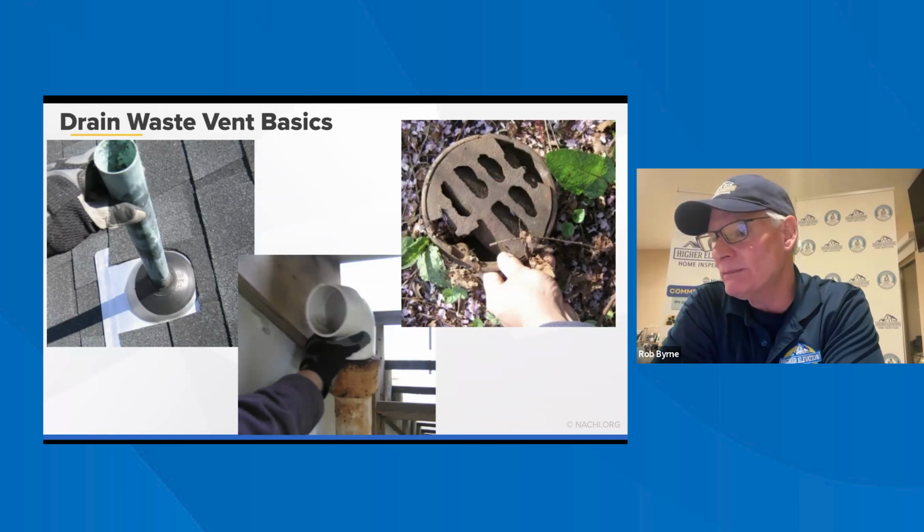You want to make sure that the flashing underneath the roof is attached properly. You don't really want to see nails going through the flashing like that. That's really not a good application. If you look at the picture on the left, there's no nails or screws going through it. The one on the left is done properly. The one on the right, they threw nails down, and you could see they did tarring or caulking around that part.